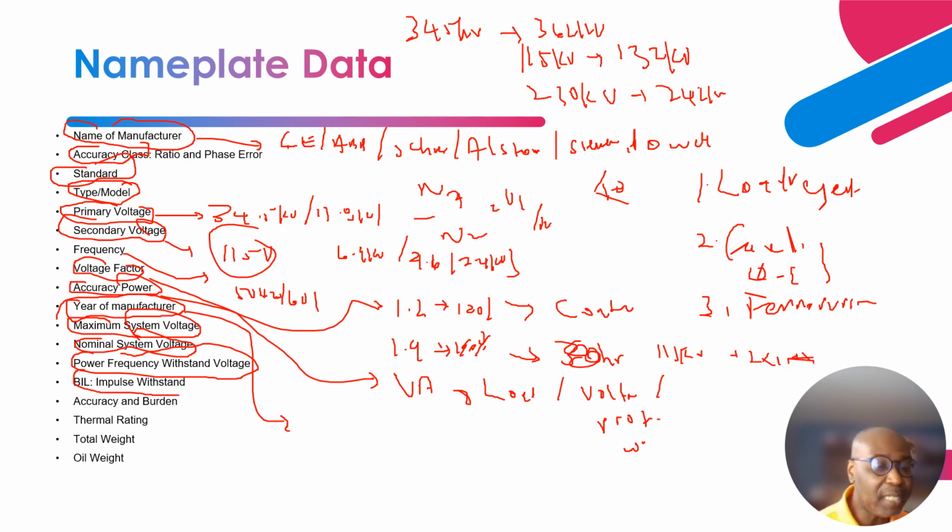Next is the basic insulation level. That is the impulse withstand. Right. Okay, so that one is due to switching. And what do you mean by switching? That is when we are operating a circuit breaker in close proximity to the location of the switchgear that houses the potential transformer or the voltage transformer. And that switching condition can create over voltages, and the potential transformer or the voltage transformer has to withstand that. Also, you can have lightning strikes, right?